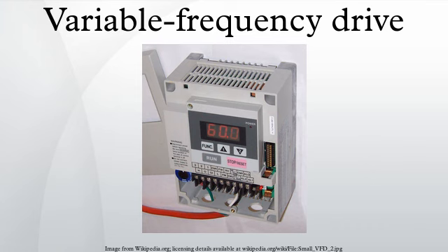Most applications involve single-quadrant loads operating in Quadrant I, such as in variable torque and certain constant torque loads. Certain applications involve two-quadrant loads operating in Quadrant I and II where the speed is positive but the torque changes polarity as in case of a fan decelerating faster than natural mechanical losses. Some sources define two-quadrant drives as loads operating in quadrants I and III where the speed and torque are the same polarity in both directions. Certain high-performance applications involve four-quadrant loads where the speed and torque can be in any direction such as in hoists, elevators and hilly conveyors. Regeneration can only occur in the drive's DC link bus when inverter voltage is smaller in magnitude than the motor back EMF, and inverter voltage and back EMF are the same polarity.